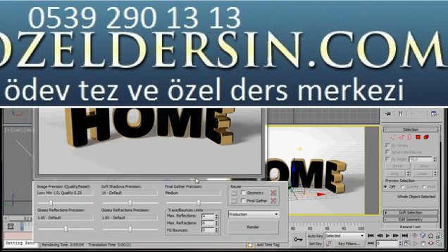Okay, now that turned out well. I re-rendered it, but this time I turned the final gathering up. I set it to medium. You can do that too if you like. Okay, let's have a look at our image. We have some nice curved edges. We've got a nice text and bevel on here, and some nice soft